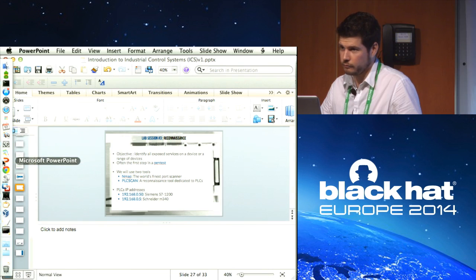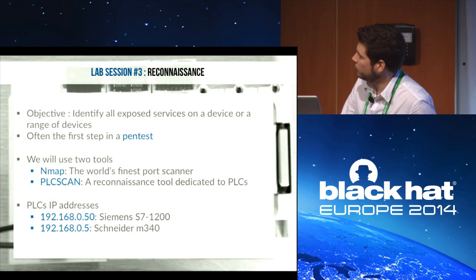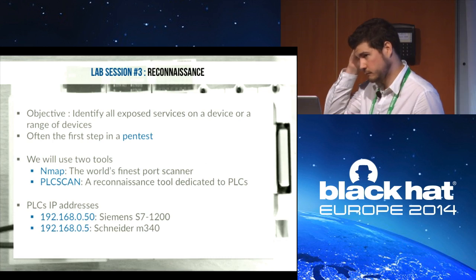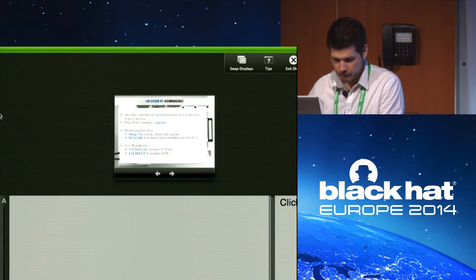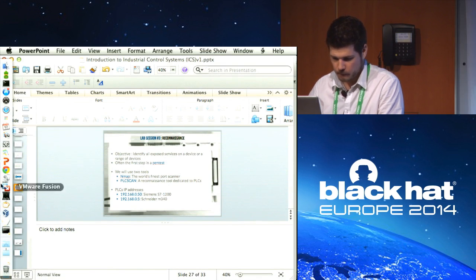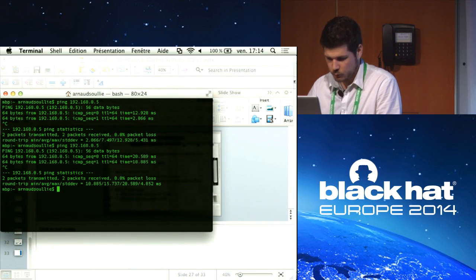Is it okay for you? Did you succeed in connecting? If so, you can try to ping the two PLCs. Here you have the IP addresses. It's .5 for the Schneider and .50 for the Siemens. They should answer to ping requests. Let me try. Yeah, works for the Schneider and for the Siemens.